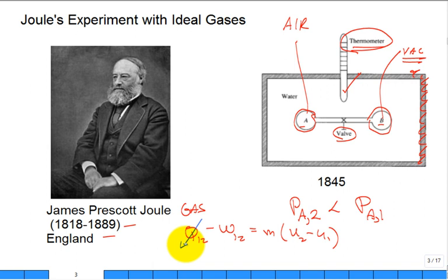Looked at his thermometer. What about this boundary work? Well, that's also zero. But hold it, it expanded. But what did it push against? Nothing. So it expanded into nothing. Hence, it really did no work. So it occupied a larger volume, but that's equal to zero. So the mass didn't change. It stays constant. So what do you conclude about the change in the U?